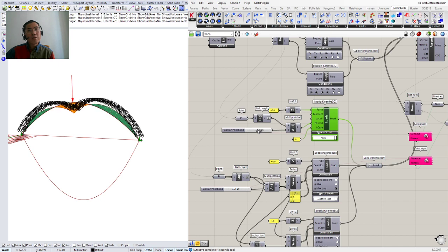And as you see, as I move the slider from 0 to 1, this point load moves along the arch. And you start to see the bending forces inside the arch. What you see when we're at 0.5, which is the center of our arch, is a very symmetric system. And then at approximately 0.25, we have the highest bending force in our arch.